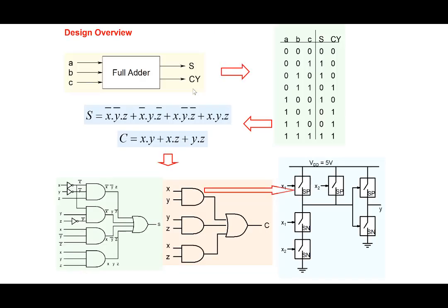All right, so we realize that there are several important steps. Whenever you want to design something, you want to design it in an efficient manner here. And we also realize that, fine, we are given the block that we want to implement, so we have a truth table, and we get a Boolean expression. And then we implement it using gates, and then the gates are implemented as transistors. So we will see that going from a truth table to a Boolean expression. Now, realize that the final circuit that you get depends on how complicated the Boolean expression is here.